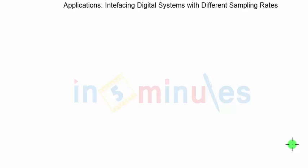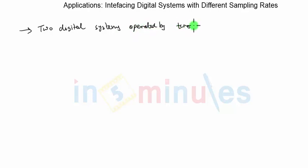In this video clip, we will discuss the second application of multi-rate signal processing, which is in interfacing digital systems with different sampling rates. Let us first of all try to understand what this means. In practice, we frequently encounter the problem of interfacing two digital systems that are controlled by independently operating clocks. So we basically have two digital systems which are operated by two different clocks.